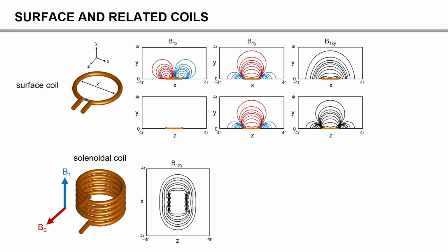However, there is a downside to this coil. The B1 field is generated along the axis of the coil, and that means the B0 field then needs to be perpendicular to that. And so if you would bring this into a typical wide bore magnet, you would basically not take advantage of the entire bore. Basically the sample would need to be inserted here and then basically rotate 90 degrees to get it into the center. And so a solenoid is a really good coil, very good homogeneity, very good sensitivity, but it is not very good in utilizing the open bore space.